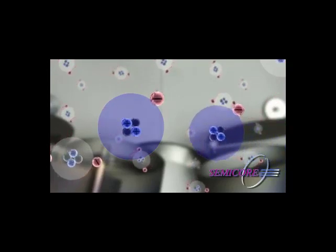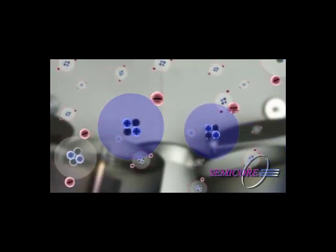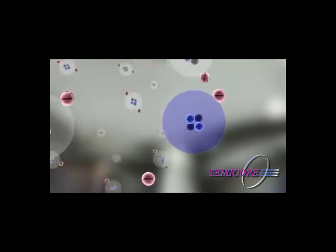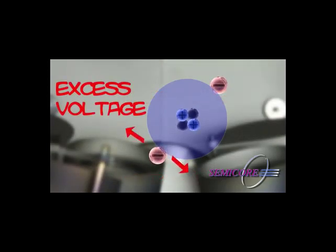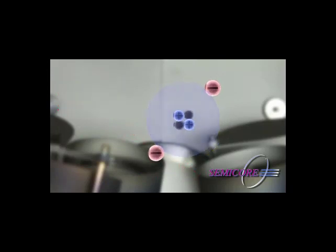The positively charged ions will recombine with free electrons to create a neutral atom again. The light from the plasma is created when the ions recombine with free electrons into a lower energy state. When a free electron recombines with an ion, it has a higher voltage. The ion needs less voltage, so this excess energy is let off as light. The light is the plasma glow that is seen during processing. This process repeats at a constant rate until the desired thickness is achieved and power is removed from the cathode.